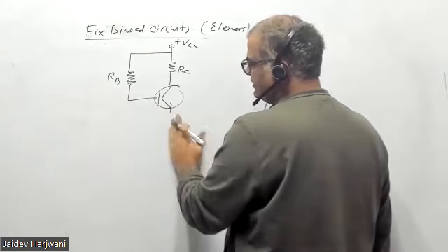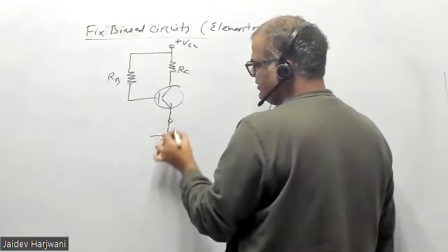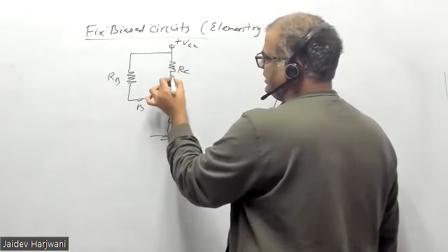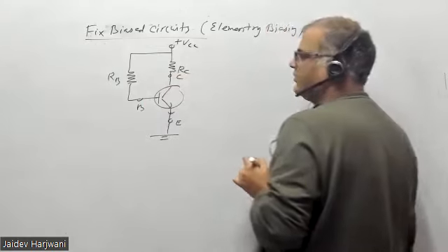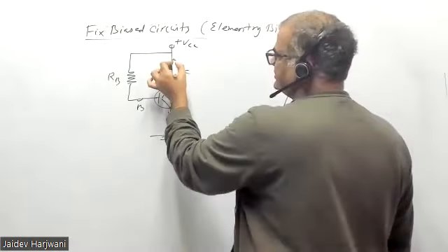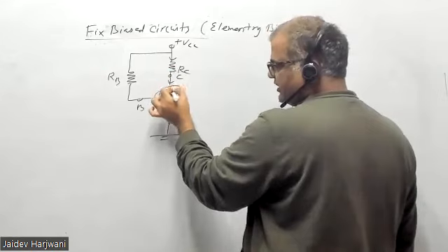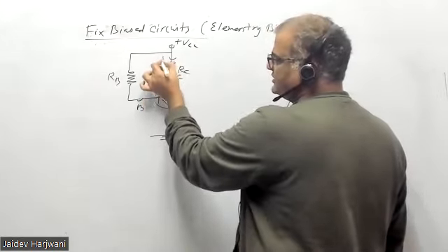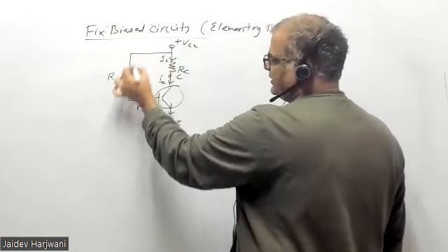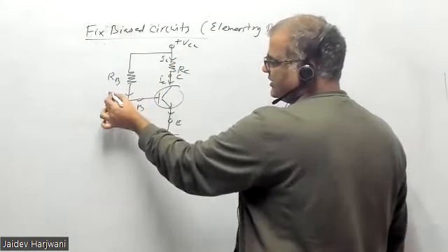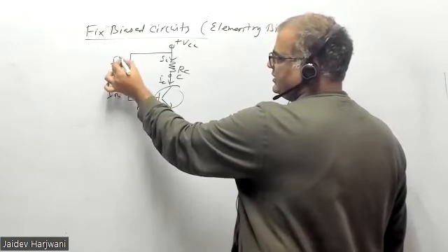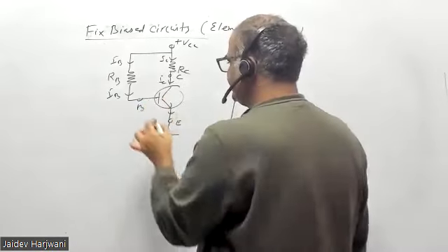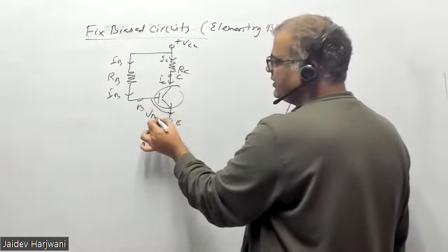So this is my ammeter. This is my base, and say this is my collector. Now the current is IC. The current which goes in the collector is called IC. Always remember, this is IC flowing here. And the current which goes in the base is called base current, IB. Nothing else is there, so this is your IB. IB is going here, and here again you have VB.